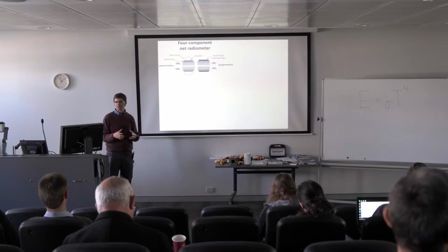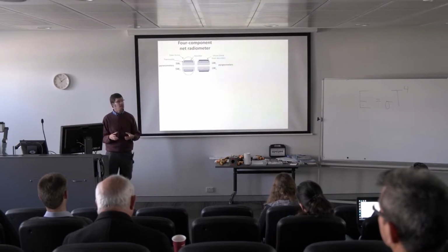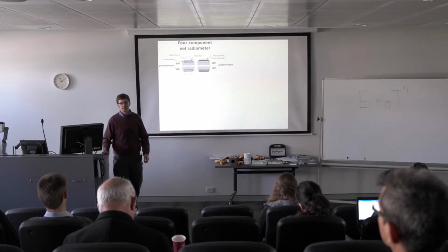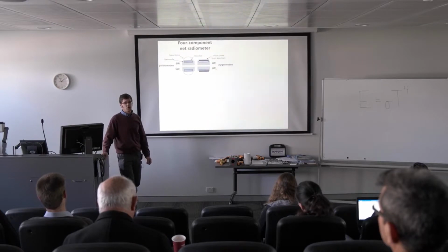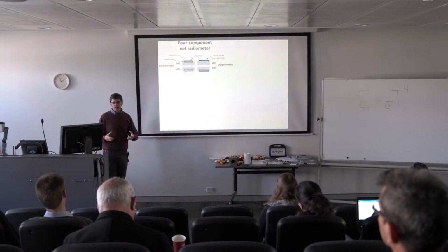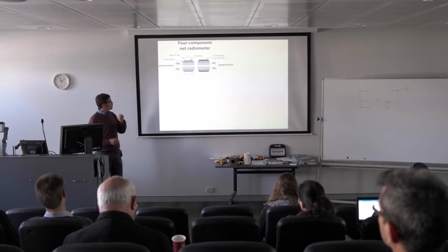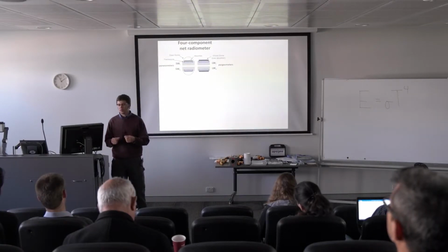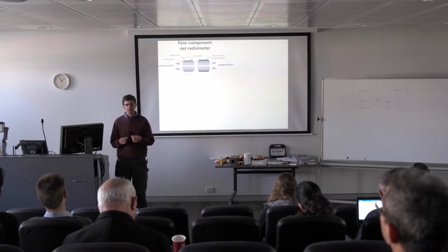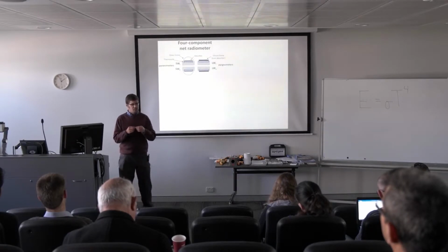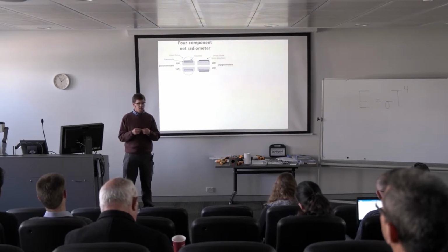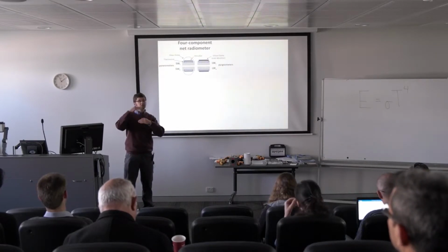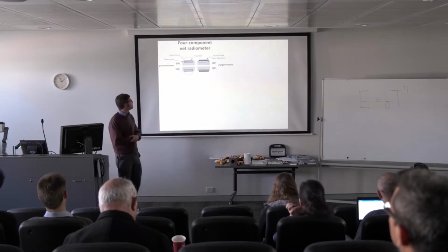Pyranometer is the name of the sensor for shortwave radiation measurements. Pyrgeometer, kind of a funny word, is the name of the sensor for measuring the longwave radiation. And so they're very similar instruments. Both of them consist of a thermopile detector, and Bruce talked about thermopile pyranometers earlier today. Essentially it's a device that measures the heat difference across the top surface and the bottom surface of the plate.